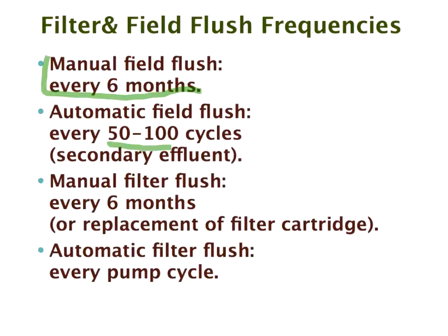Is that excessive? Yes. Does it cost anything to do it excessively? No. The amount of energy used to flush is so small that it really doesn't matter. If you flush once a week, 50 times a year, or 100 times a year, the difference of cost is insignificant. Manual filter flush every 6 months. If you don't have automation, I think that you should not go over 6 months before maintenance cycles. If you're fully automated, then of course a year is a lot easier.